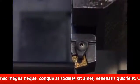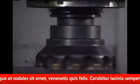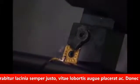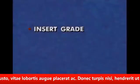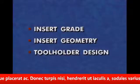Cutting tools fall into two broad classes: single point and multi-point tools. Turning uses single point cutting tools, usually coated indexable carbide inserts. Selecting turning inserts involves choices of insert grade, geometry, and tool holder design.